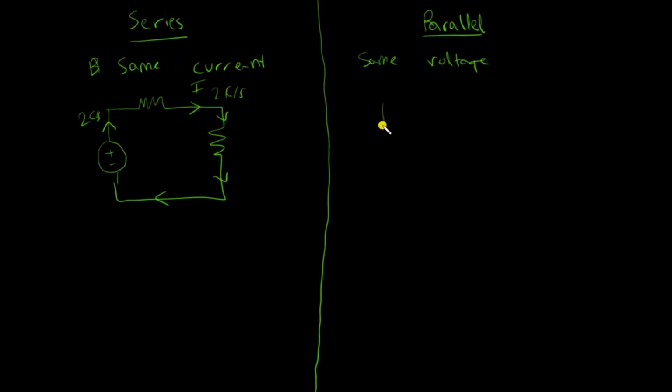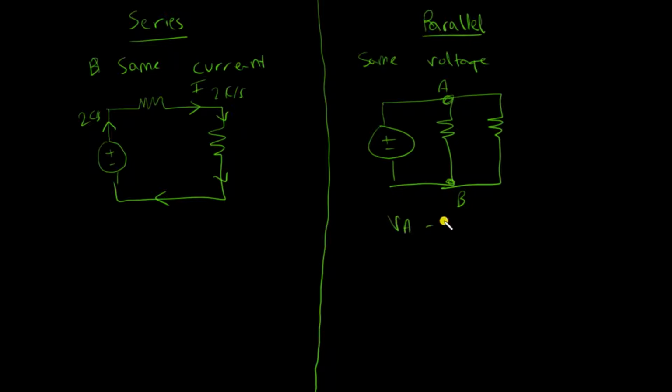However, if I have a voltage here and I have a resistor here, this single node pair circuit, as discussed in the previous practice example, has just two nodes, node A and node B. All of the elements are connected between these two nodes, and hence the potential difference across each element is the same, which is basically VA minus VB. So this is what a parallel configuration is. Sometimes it is pretty easy to see how the current is the same in all elements or the voltage is the same across all elements, but sometimes it gets difficult when the circuit becomes a little too complicated.